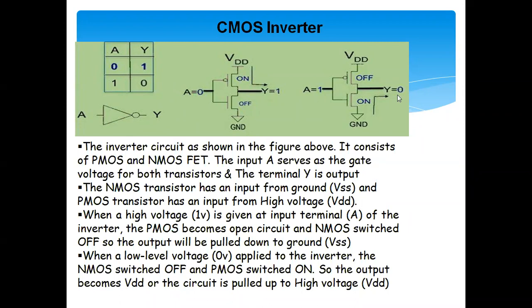That means what? The drawbacks of each other, by connecting in series with each other, we have compensated, and now we are getting strong logic 1 as well as strong logic 0, right? Strong logic 1 is passed by PMOS and strong logic 0 is passed by NMOS.